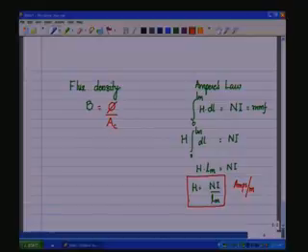So if we have the cross section area of the core and flux is flowing in this direction through the core, this cross section area, which is orthogonal to the flow of the flux, is AC. So flux per unit area has units of Tesla. Flux has the unit of Webers, and Webers per meter square is Tesla, named after the famous scientist Tesla, who has contributed